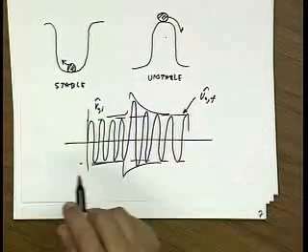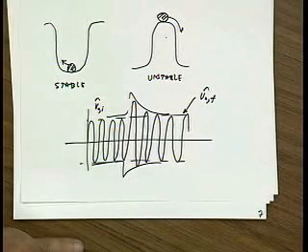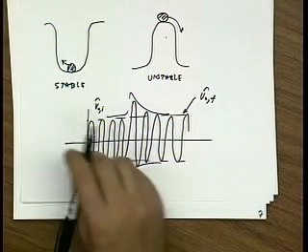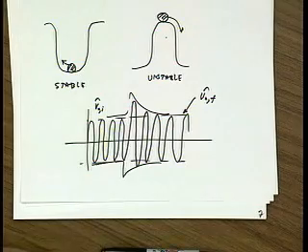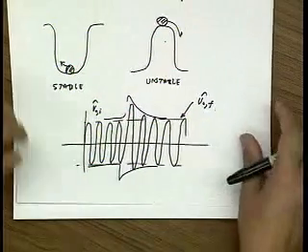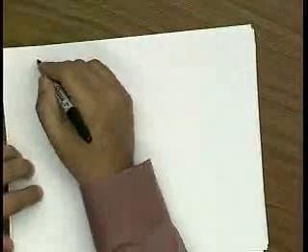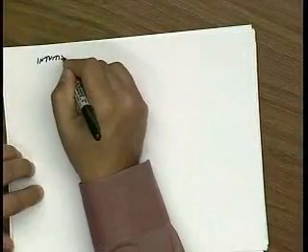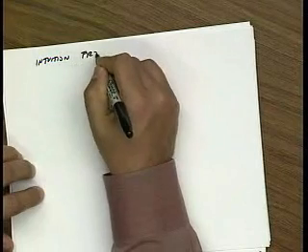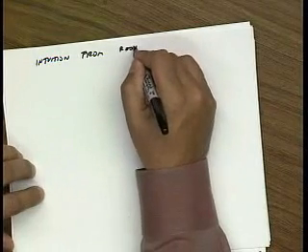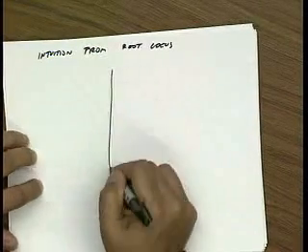If it comes back to the same initial amplitude, then I can say that the system is stable. Okay? Now, the reason that this happened is actually related to Debo's question. So, let's use our root locus to gain some intuition.